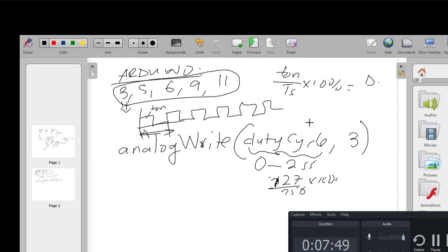And so what we are saying in this case is that, with PWM, we can have a switching period of TS. And actually, an Arduino output should be about 500 Hz. Now, I've got to check that one out. Pins of Arduino can put out a maximum of about 500 Hz.